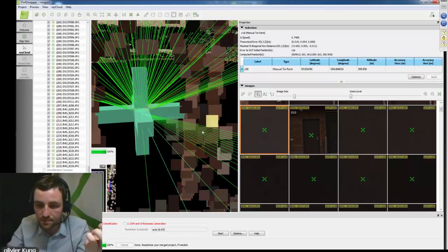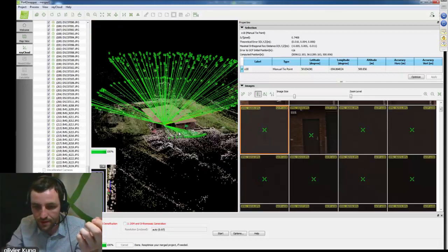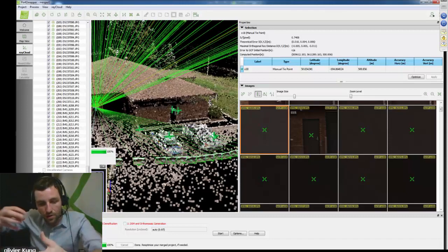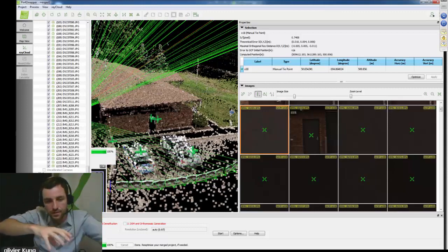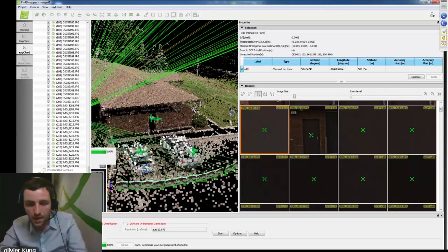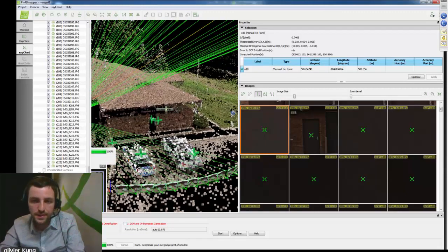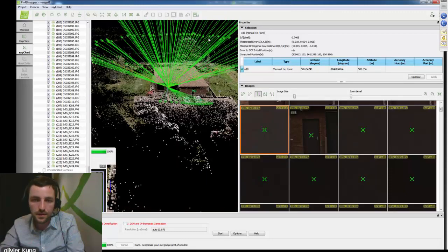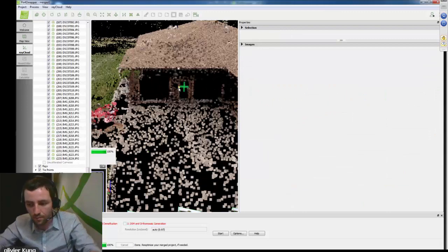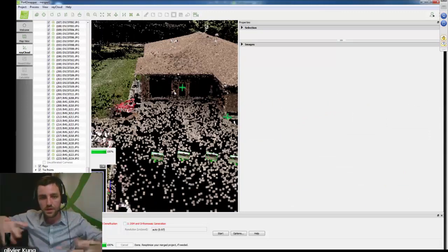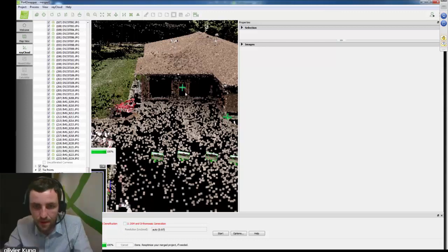The reason is because my tie points that I created right there are very localized to the front of the project. So a small misalignment in angle could have big consequences later on. So a good practice right now is to add a few more tie points in more spread out parts of the project to make sure that we correct for these small inconsistencies.